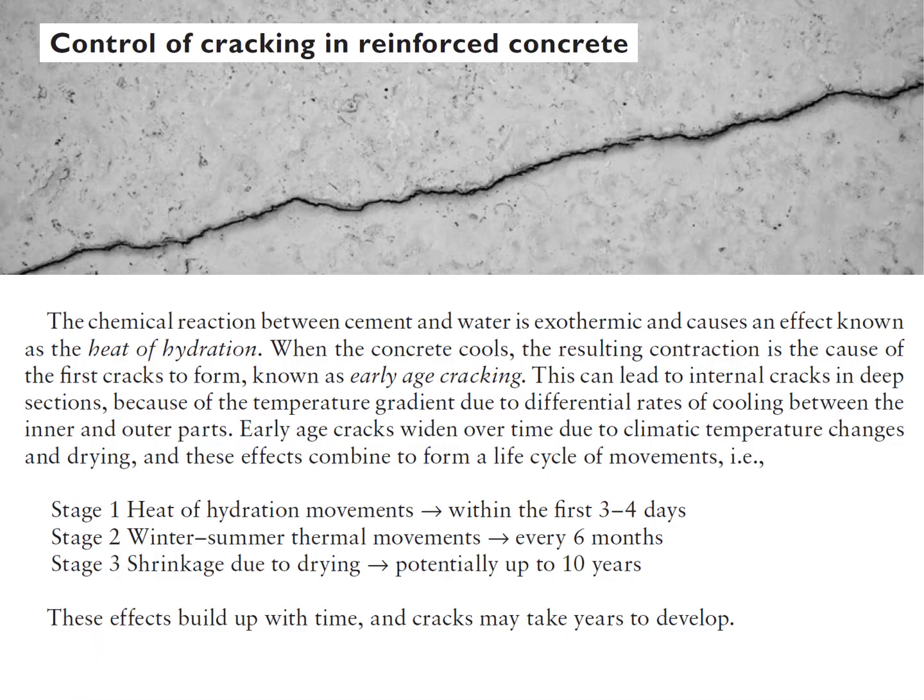Cracking is normal in reinforced concrete. If cracks are less than approximately 0.5 mm wide, they will not normally cause corrosion, which is normally caused by the permeation of dissolved salt or carbon dioxide through the cover. Cracking needs to be controlled mainly because it is unsightly and causes complaints.